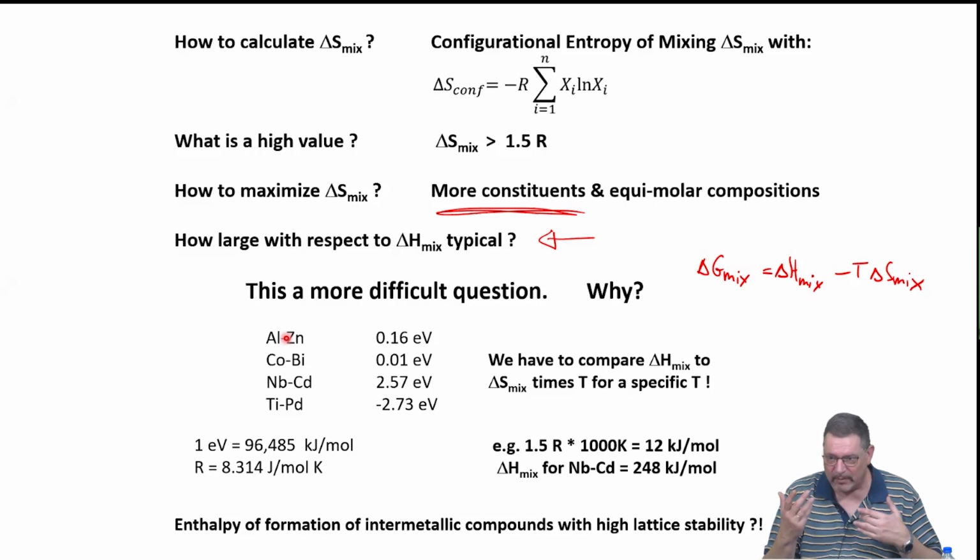For example, in an aluminum-nickel system, the aluminum-nickel phase is so stable, it will always form. Even if you prevent it by some clever processing, you will look in the short-range order, and it will still be the aluminum-nickel phase. Nothing you can do about it.